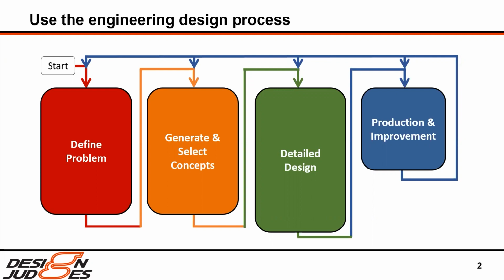But the most common mistake made by inexperienced designers is to only get a general idea of your objective, and then to begin creating a solid model and performing stress analysis on the first idea you have. When you do this, you're really going to miss out on developing a much better solution, and will often spend a lot more time iterating in the detailed design phase than you gain from skipping the first two phases. So you can see here the four phases that I roughly break them into.